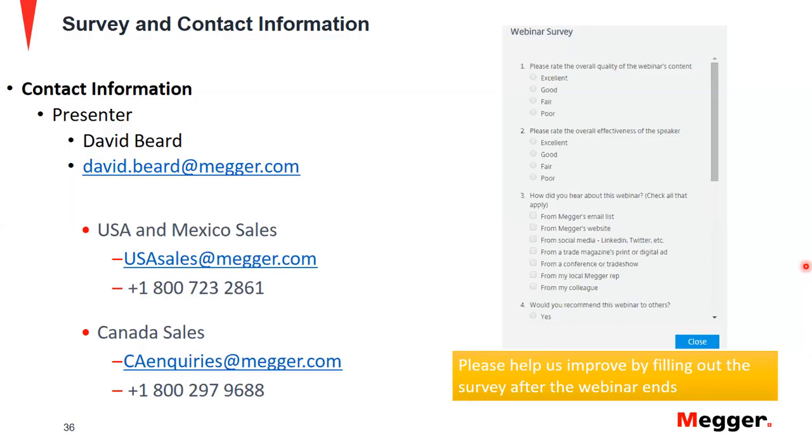Hey, Mike, before we proceed, I would like to point out another answer of mine, which I told about the timing unit on the breakers. I see that Mariano is having an objection in there. He is referring to using a primary current injection test set, which is absolutely correct. Definitely, primary injection test sets can be used to inject the values of high currents on the primary breakers. And then you can measure the trip time using the primary injection test sets.